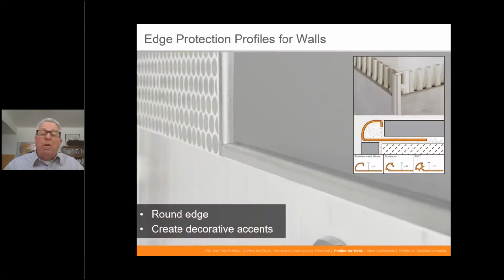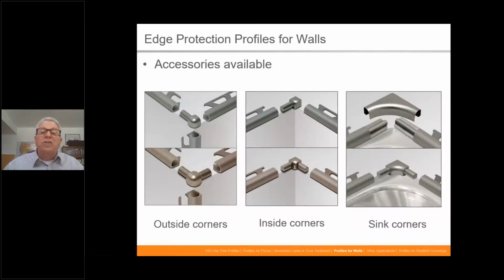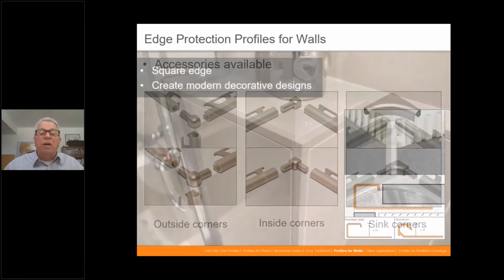Another one that's very popular is one that kind of mimics a quarter round, because we had quarter round in the tile industry for a very long time to do those transitions when everything was a mortar bed application. So the quarter round is very popular. And one of the other reasons why it's popular is because it comes with inside corners, outside corners, all types of pieces you need to do three-way. So keep that in mind, that's very popular there.